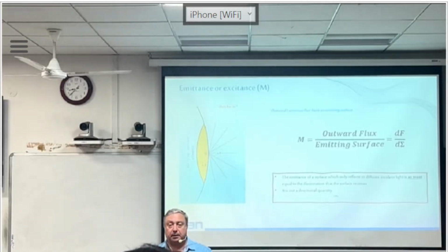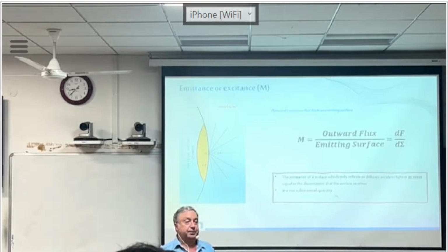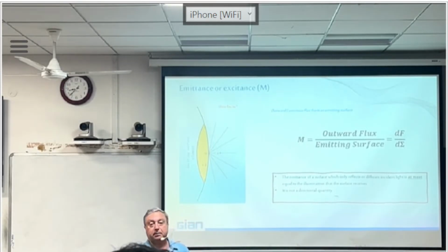You will see at the end of this lecture that between the illuminance arriving on the table and the emittance of the table as a secondary source, you have the reflection coefficient of the surface. The reflection coefficient could be equal to 1 at best, and then emittance equals illuminance, but in many cases the emittance is lower than the illuminance.